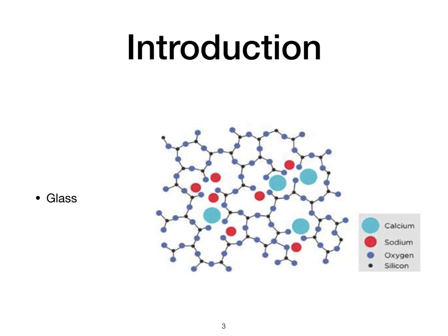Glass is an amorphous material that lacks a long-range periodic crystalline structure. Glasses can be formed through several methods, but the most common method involves heating raw materials into a molten liquid and then rapidly cooling the liquid in such a way that atoms remain in a random atomic arrangement. Here in the image you can see the 2D representation of glass. The additional silica bond to oxygen is not visible, but in 3D representation it would be visible.